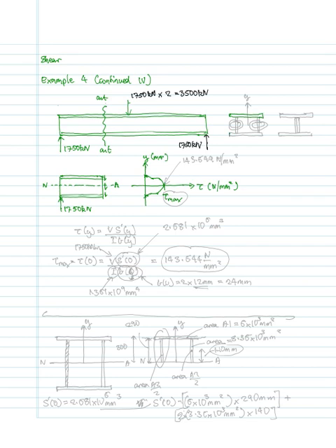So if I put that tau, and remember the units of y is in millimeters going upwards, and the units of tau is a stress, which is force over area, so that's newtons per millimeter squared, and then that value there is going to be tau max.